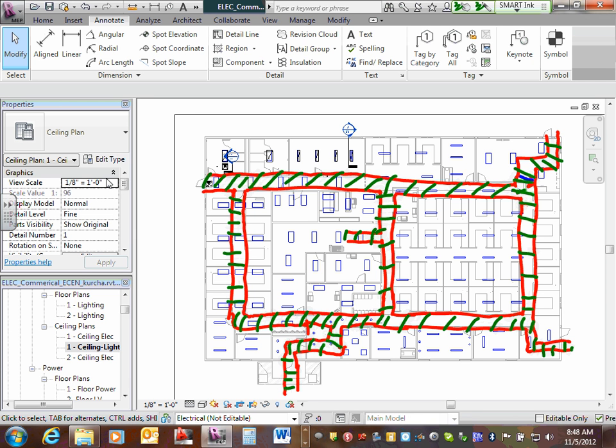Who decided the egress path? The architects. When they design a building, they don't want to trap the people inside of the building. They don't want the people to panic, right? So for safety, we have to design an area, typically hallways, almost always hallways. Can you guys see that? If you want to know where they go, almost always hallways. Hallways are your egress path. Or if you have a big hall where people are assembled, you have to have an egress path. So look at this.